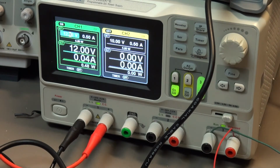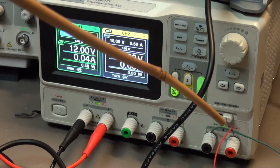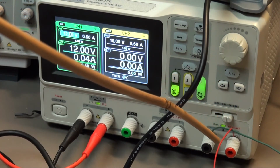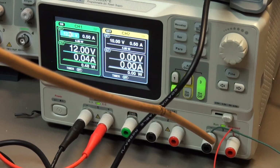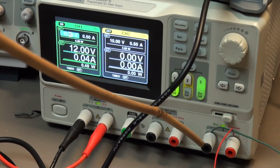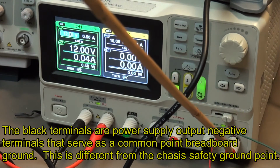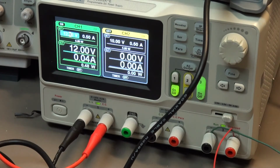The Electret microphone, Max 4466 is the number of that one, requires a 5-volt power. So as stated earlier, this power supply is capable of producing that. It has a dedicated output with just 3 settings. Right now it's set to 5 volts, and that's another common ground point, and that's the power for the little microphone that will be showing you very shortly.